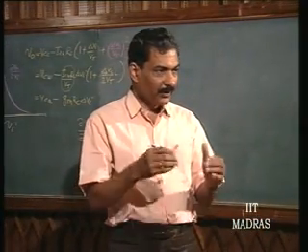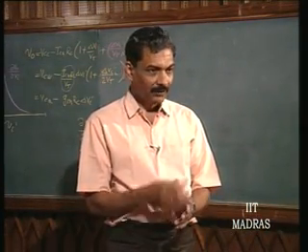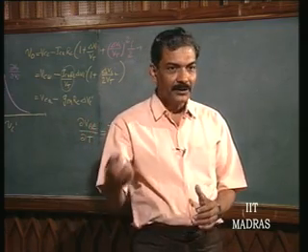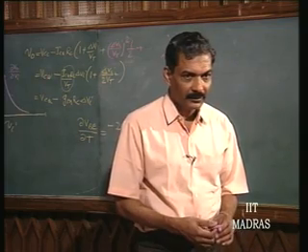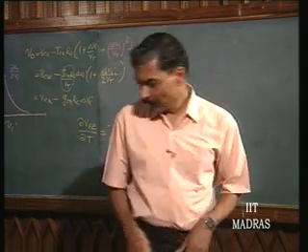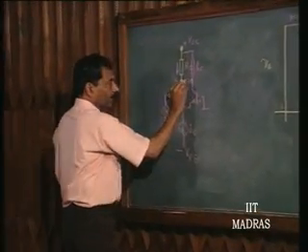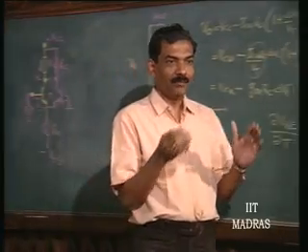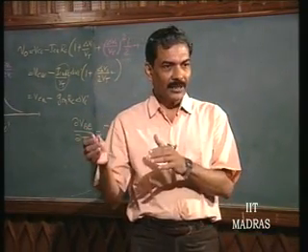So, Vi by 2 Re into Rc is the single stage gain with a minus for the first stage, and for the other stage it is plus Rc divided by 2 Re. Is that clear? So, if you take the differential output as the output, what will you get? One is going to be minus Rc by 2 Re, another is plus Rc by 2 Re.